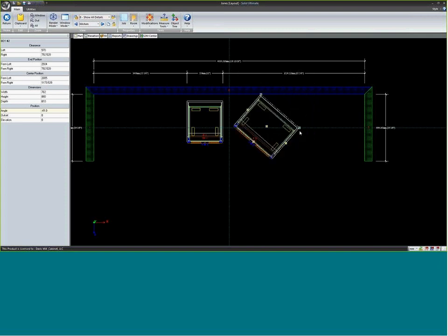If I rotate this cabinet, I have rotated around the y-axis. So I have changed the AY parameter. By the right hand rule, rotating around the AY parameter would be like your hand if your index finger were the axis. If you want to rotate something around the x-axis, the AX is rotating around your thumb as an axis.